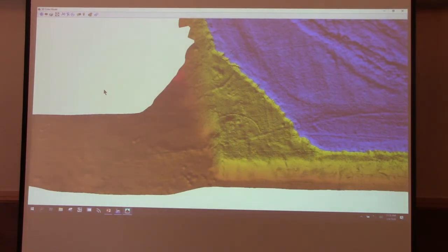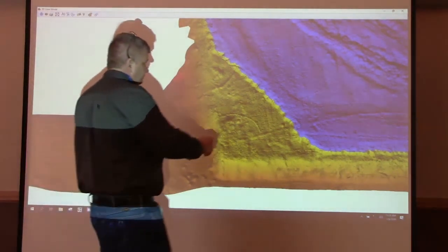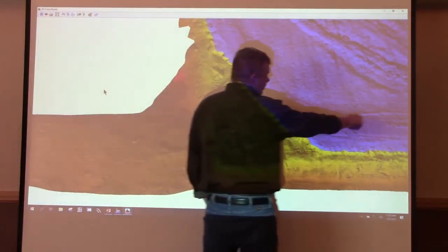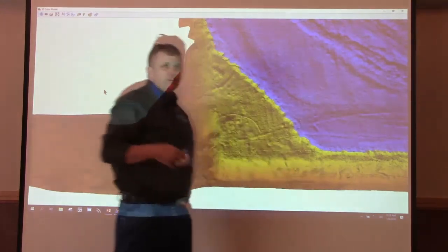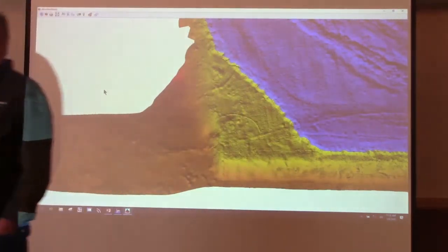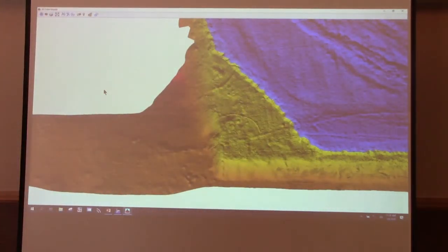You don't want to output data sets that are multiplied, but for display purposes and for contouring, you can actually see out here a lot of the ridges became a lot more pronounced and easier to define, easier to see. Now if we export that geotiff again and put it into a report, put it into AutoCAD or Google Earth so the customer can look at it, it's very dramatic where those ridges are, where those things exist.